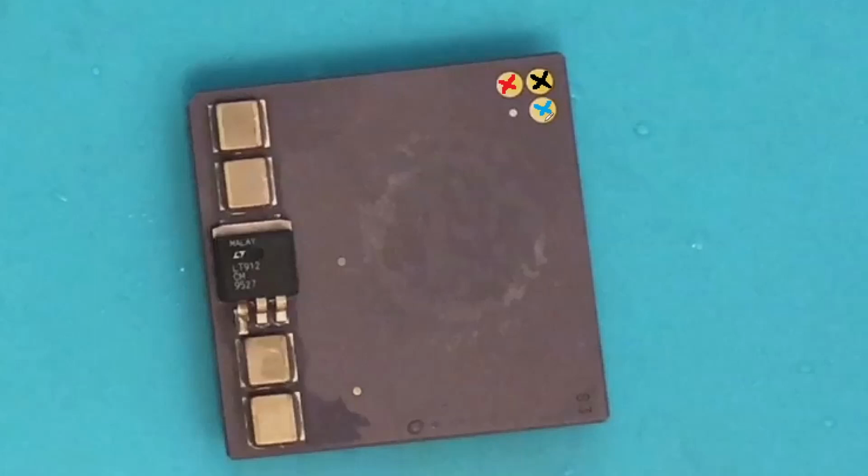So basically this pin here is a digital input that just tells the CPU if the fan is working or not. If you don't have a fan attached, this pin is around 2.5 volts. But then the fan pulls this pin to the ground. Now if you slow down the fan, at some point the fan fails and stops pulling this to the ground, so it returns to 2.5 volts. If it detects a fail, it continues to signal a failed fan until you actually completely cut the power.